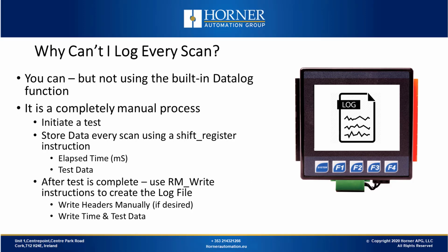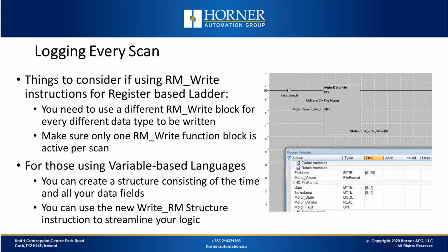Why can't I log every scan? Well, actually, you can, just not with the built-in data log function. It is a completely manual process, and you start by initiating a test like we did in the demos. Then you can write some logic utilizing a shift register to scan every record. The time and the data from a millisecond based timer are going to be recorded in internal registers. Once your test is complete, you're going to use the removable media write instruction to create your log file manually.